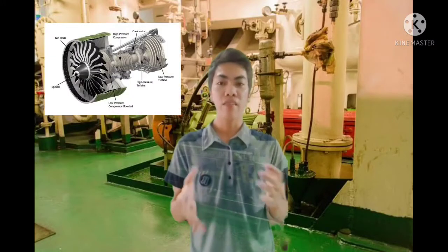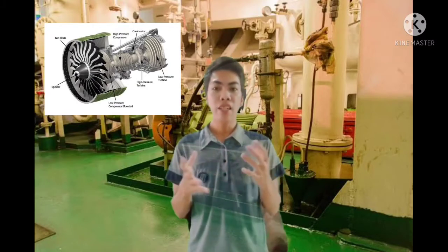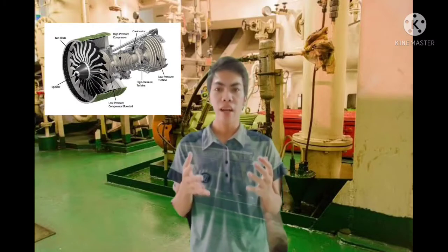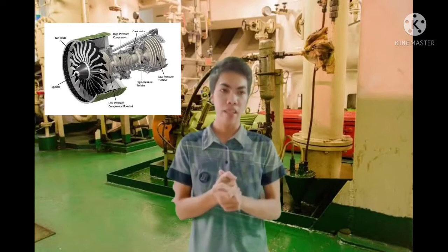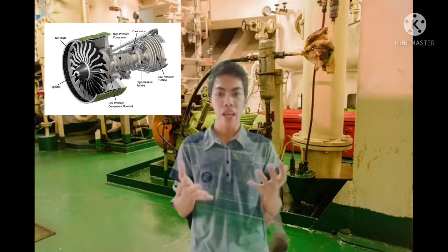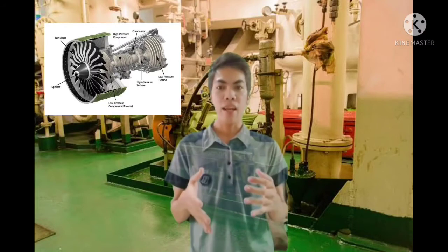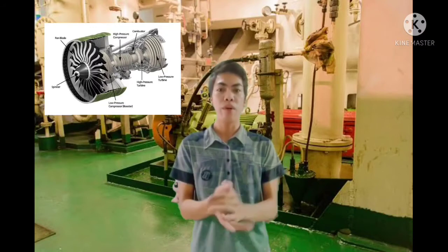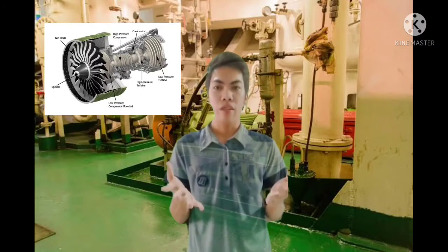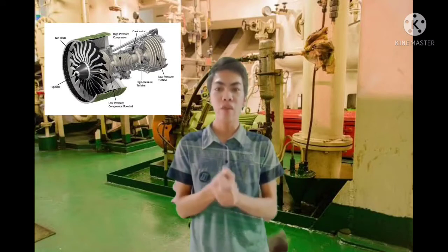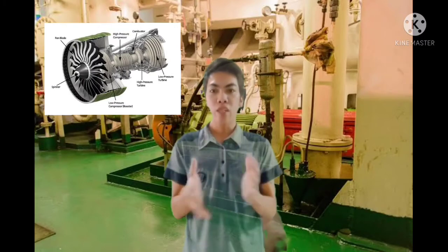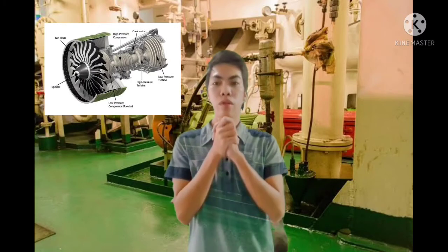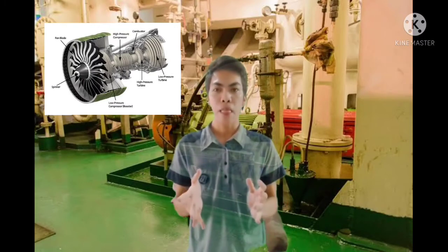So first is the axial compressors. Large fans pull in air at high velocity. Stationary fan blades are placed to guide the air to the next fan. As the space between fans gets smaller, the high kinetic energy of the air causes it to pressurize. Pressurized air is forced through the outlet.